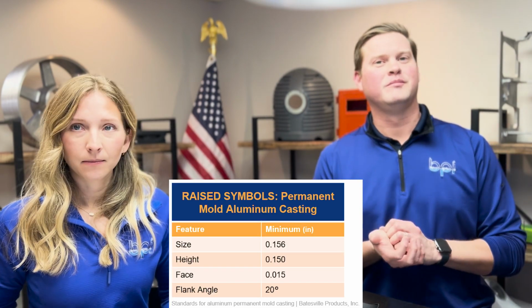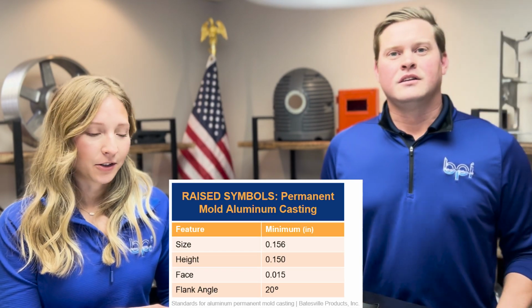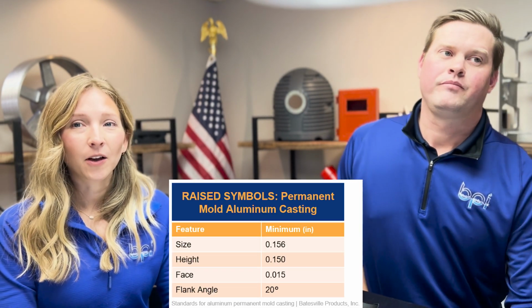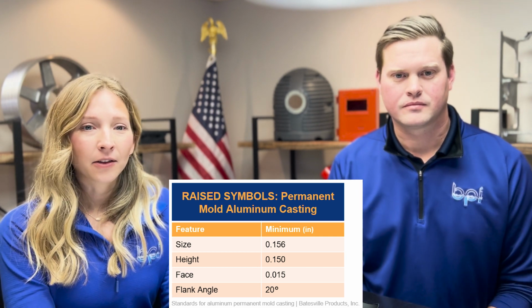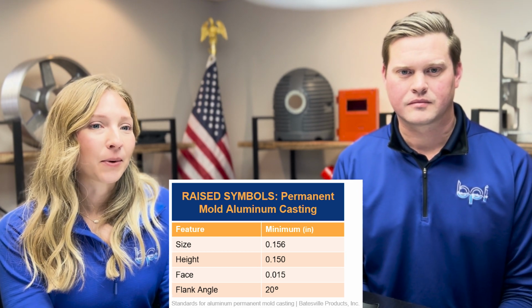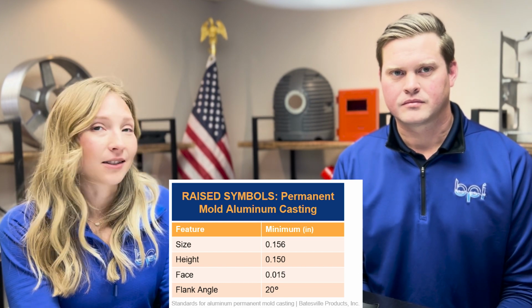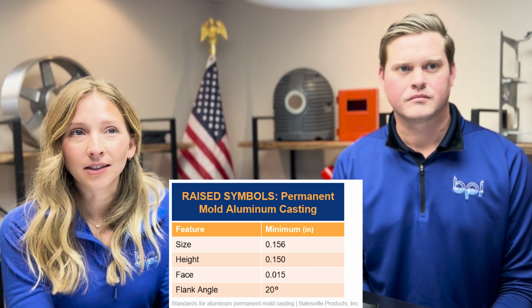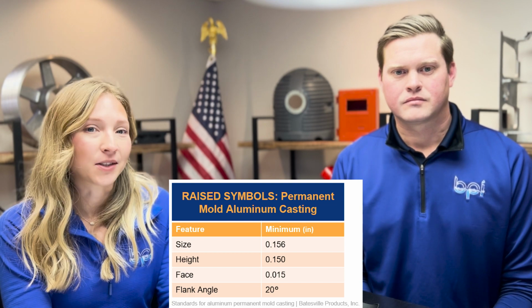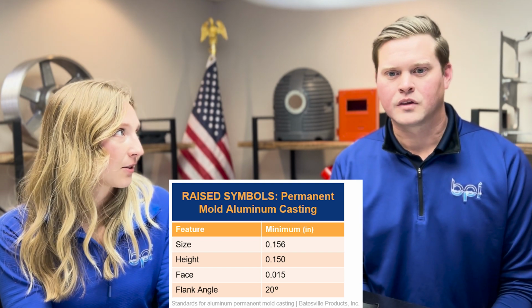Yeah. Logos, symbols, and letters. You're going to apply essentially a lot of the same thought processes we used in the beginning to this. So draft, make sure you have enough draft on these logos, letters, and symbols to make sure that the impression sticks. You have anything else to add to that?